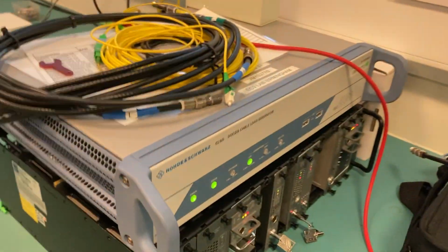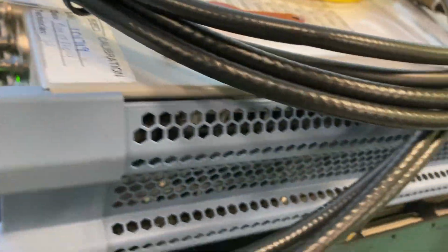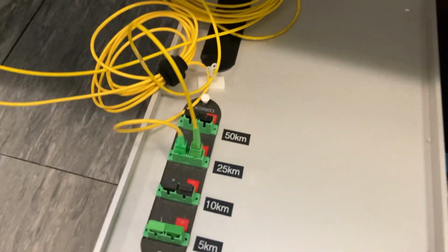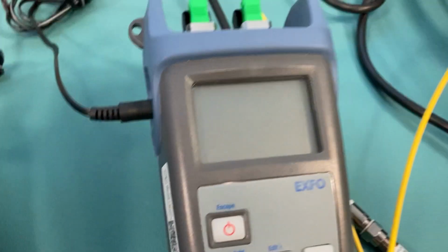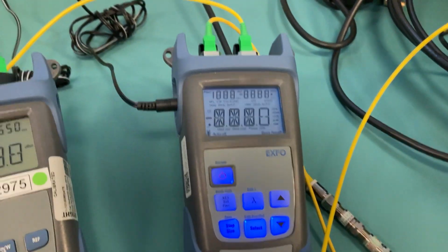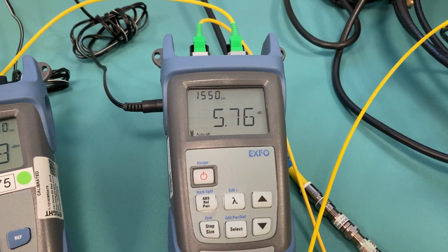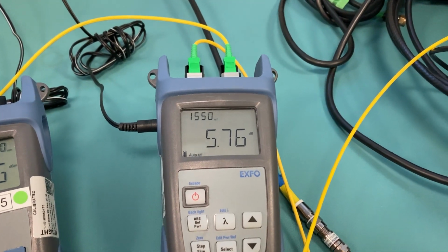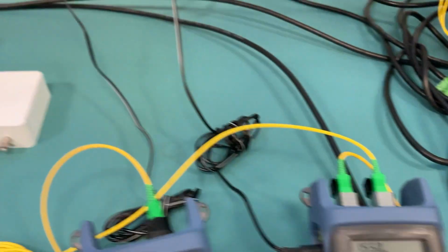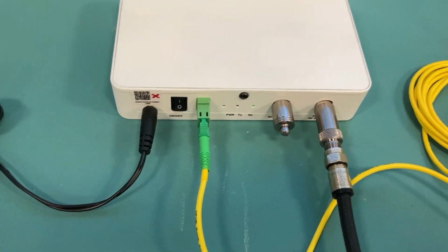Anyway, so that's what the channel source is going into the laser. Out of the laser, we are into 25 kilometers of fibre in the box down here. Out of the fibre into an EXFO optical attenuator, so that guy boots up. So 5.7 dB of attenuation in there at the moment, and that's basically set up to give me approximately 0 dBm here at the input to the ONU.